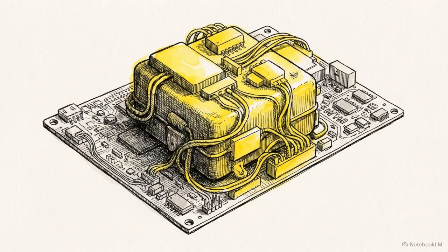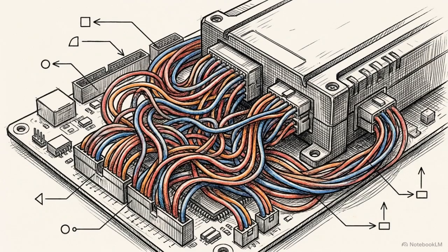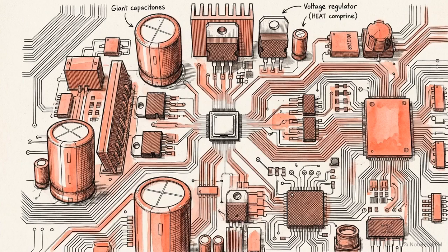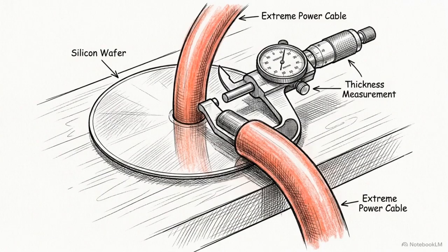But RSL introduces severe architectural costs. It absolutely requires an external random number generator running constantly to feed the mask, and a global enable signal to time the logic evaluations, both of which cripple the maximum operating frequency of the chip. While masking successfully bypasses the need for physical silicon symmetry, it shifts the engineering burden directly onto complex architectural overhead and severe performance degradation. DPA resistance is a strict economic trade-off. It is bounded entirely by the physical limits of a chip's available silicon area and power budget.